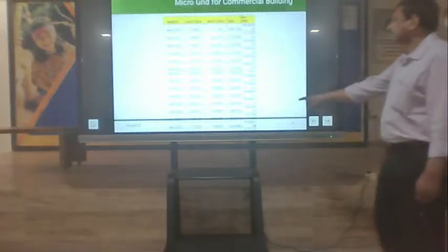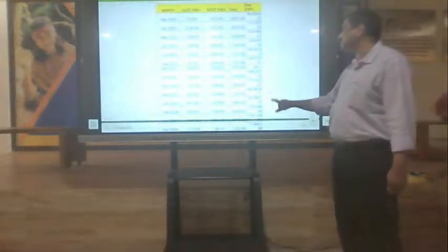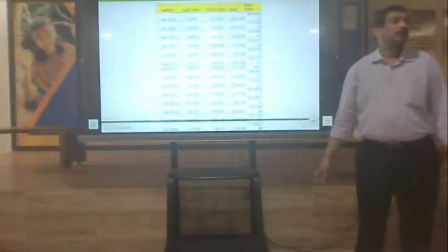If we use the DC-DC converter, which maintains a constant voltage, it is regulating that. What it is doing is tracking the maximum power point. How does it do this? As I told you in the earlier case, what is happening when my solar energy is there and I load it? The terminal voltage falls down, right?